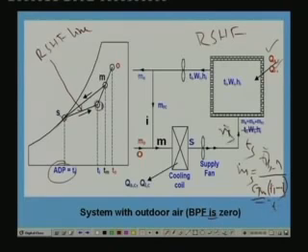Once we know the mass flow rate of the supply air, then again performing latent cooling load balance and the total cooling load balance, we can find out the supply air humidity ratio and supply air enthalpy. So we can fix the state of the air. In fact, for this simple case, once you locate this point, you can directly read these values from the psychrometric chart.